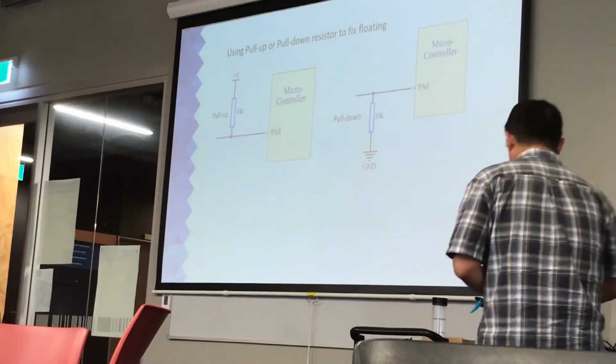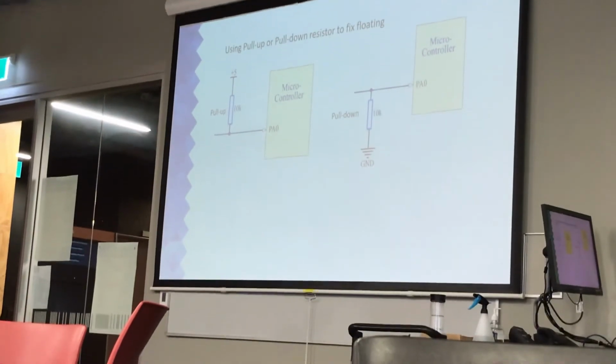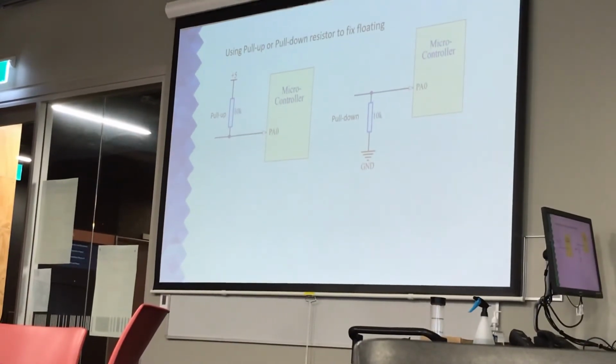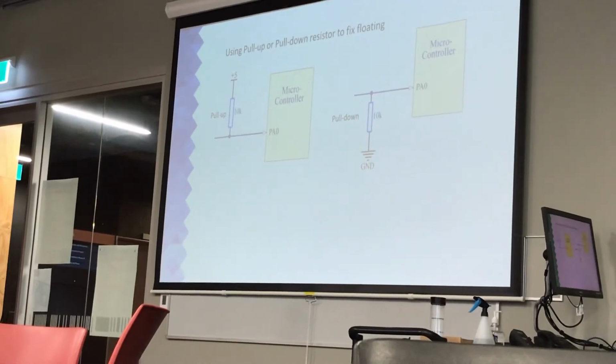So if I have a microcontroller, with PA0 and a push button that goes to ground, that is called floating.